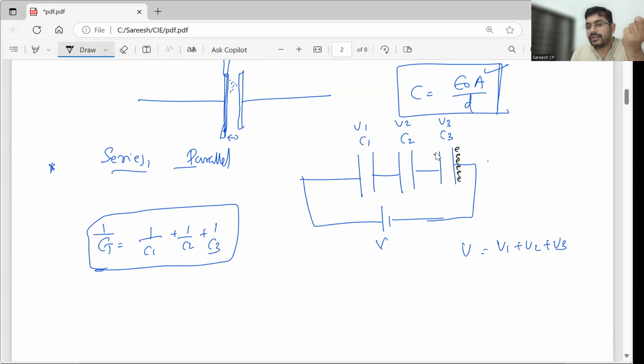So here, the electron over here will be left, and the electrons from here will move over here. This electron will move over here, this electron will move over here. Since there are 6 electrons on one plate of the capacitor, the other plate of the capacitor will have 6 absent electrons, and those electrons will go to the next capacitor.